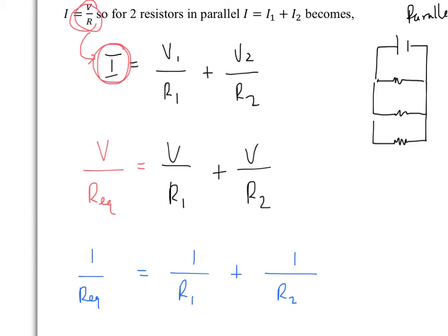Okay, but this is the idea. To generalize, we can write plus ... 1 over Rn. So if you want to find the overall resistance in a circuit, you need to add their reciprocals and then solve for REQ. We'll do that in an example real quick. Okay, so this is different than all of the laws. But again, you don't have to memorize any of these rules we came up with.